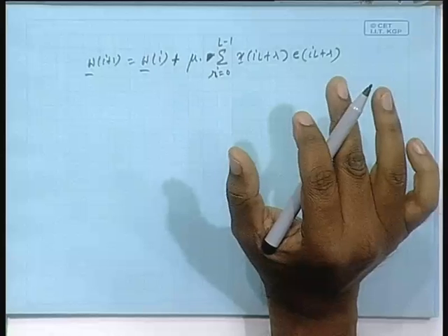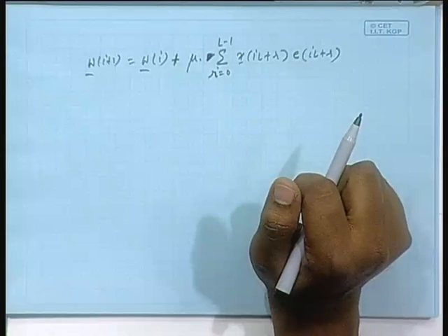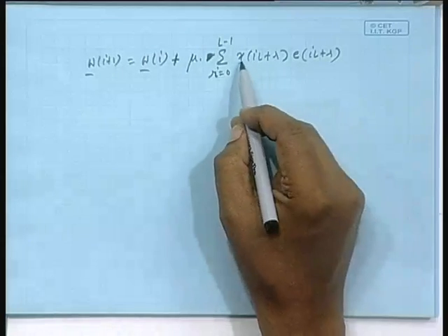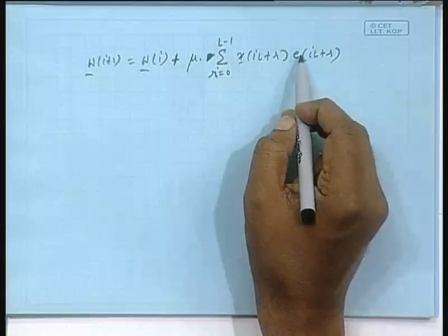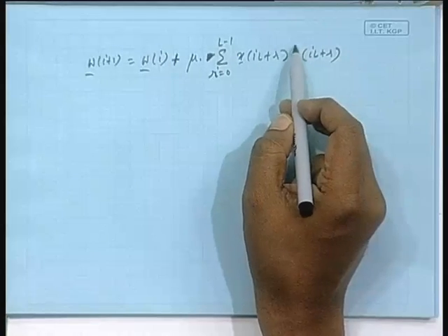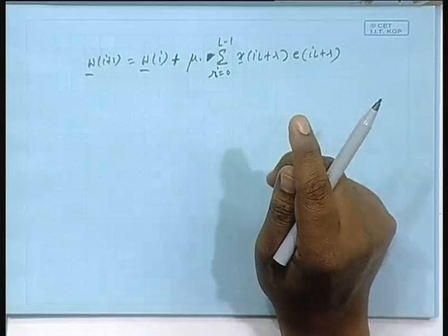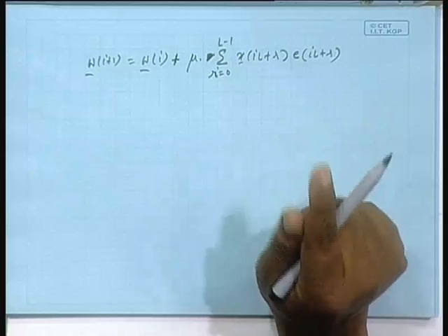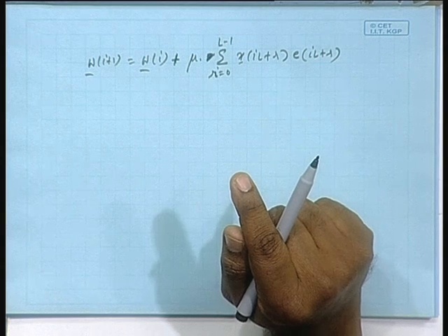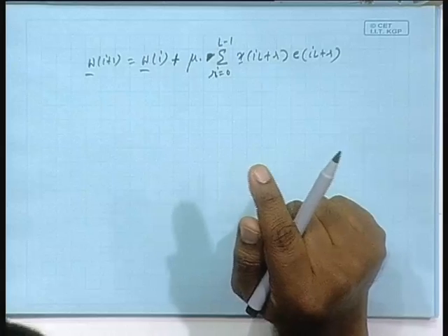You know what change will be there in the complex case? In the complex case, this data vector will be as it is, there will be a star on e, and in the filter part it will be W transpose x(n), that is, W Hermitian times x(n). That was the only difference.